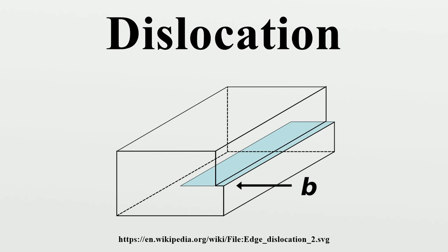When metals are subjected to cold working, the dislocation density increases due to the formation of new dislocations and dislocation multiplication. The consequent increasing overlap between the strain fields of adjacent dislocations gradually increases the resistance to further dislocation motion. This causes a hardening of the metal as deformation progresses. This effect is known as strain hardening.